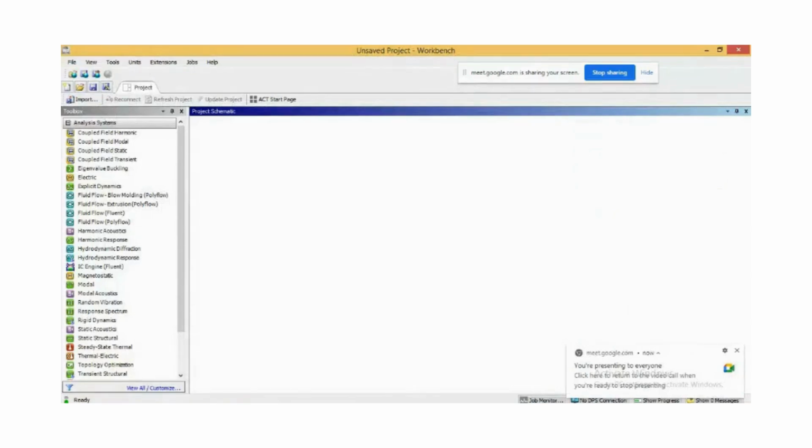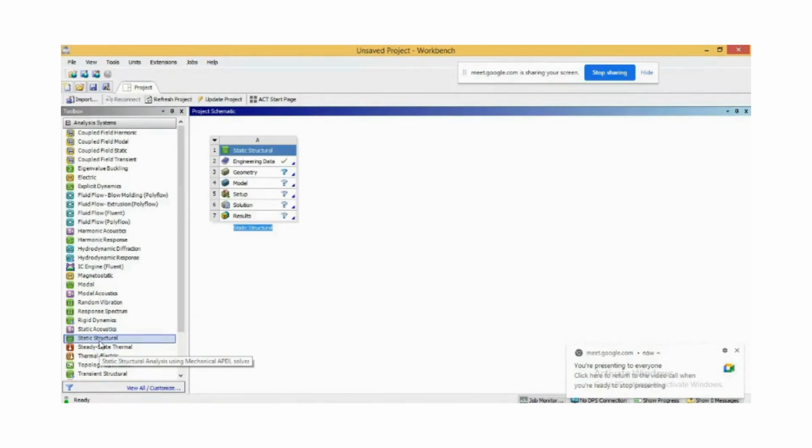Okay. Now we are doing the static structural analysis using 3D elements. For static structural analysis, we observe the same steps, 7 steps are there. Types of analysis: static structural, engineering data, material property, geometry modeling, meshing, application of load and boundary conditions, then solution and result viewing.